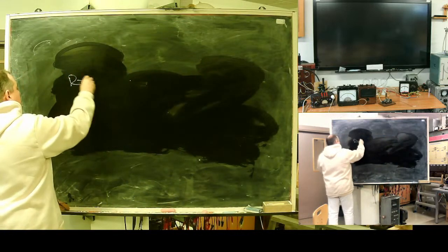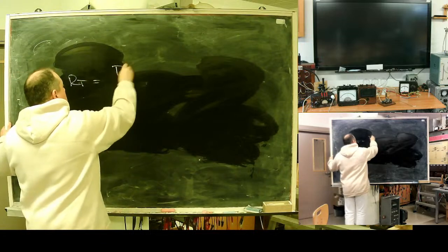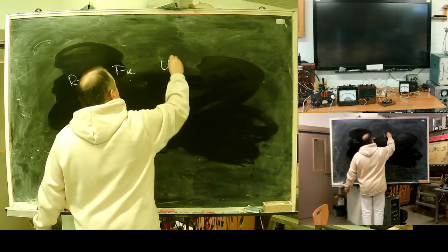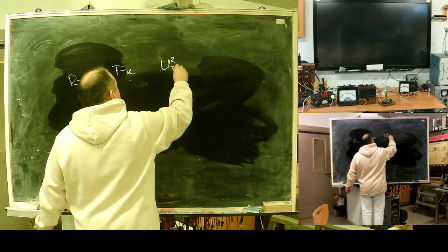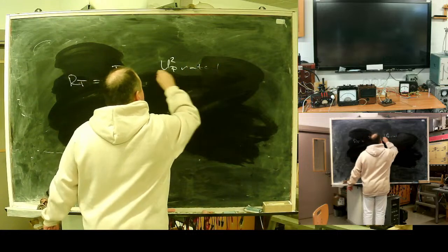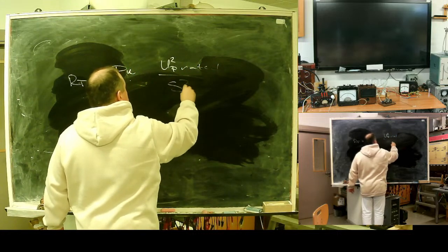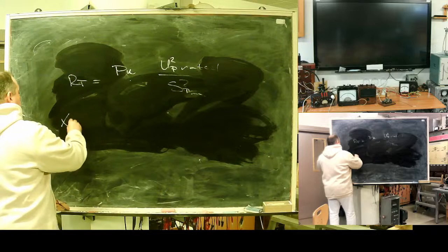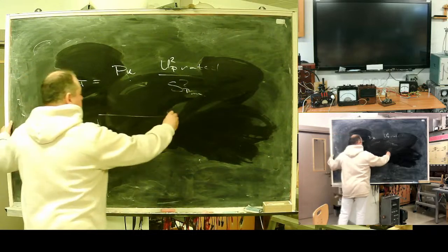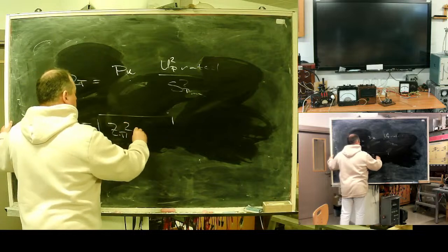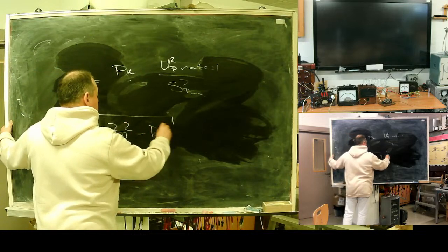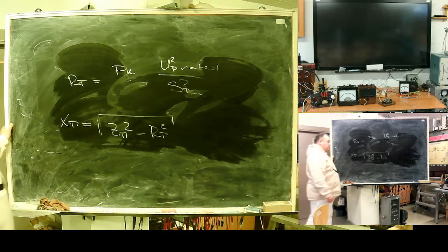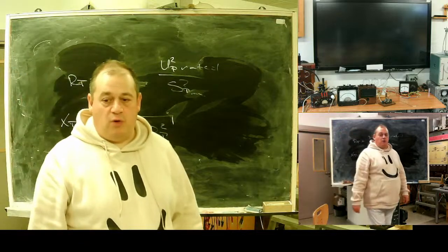The equivalent resistance of the transformer can be found as this short circuit power multiplied by the square of rated voltage, divided by the square of the transformer rated power. And transformer reactance can be defined as the square root of Z transformer squared minus R transformer squared, from the full resistance. This is the general thing about the transformer.